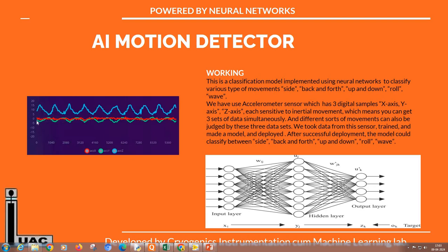Then what happens, suppose you take a window of 1 second. 1 second is nothing but 1000 milliseconds. Every 1000 milliseconds it will sample for each signal 100 data. That means 10 milliseconds each sample. So you can say, in essence, from 3 sensors you get 3 different 100 data.